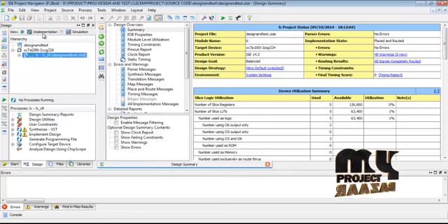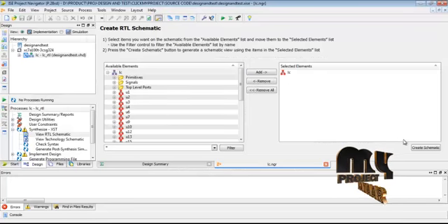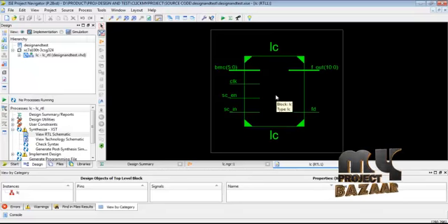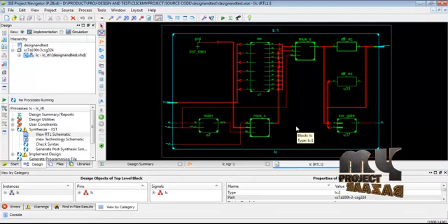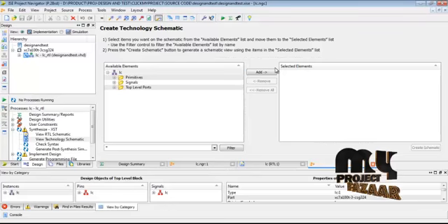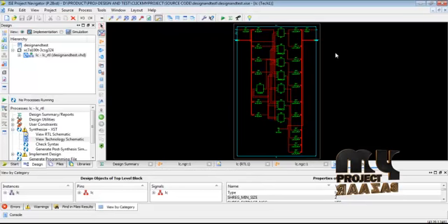Then to calculate the implementation process, we create the view RTL schematic. This is our LOC and LOS based testing architecture. Here we develop the benchmark circuit and the overall combination in the RTL diagram. The RTL diagram represents the logical blocks placed in our testing architecture. Then we go to the technology diagram. The technology diagram represents the lookup table and flip-flop pairs, and the input output connections placed in our testing architecture.